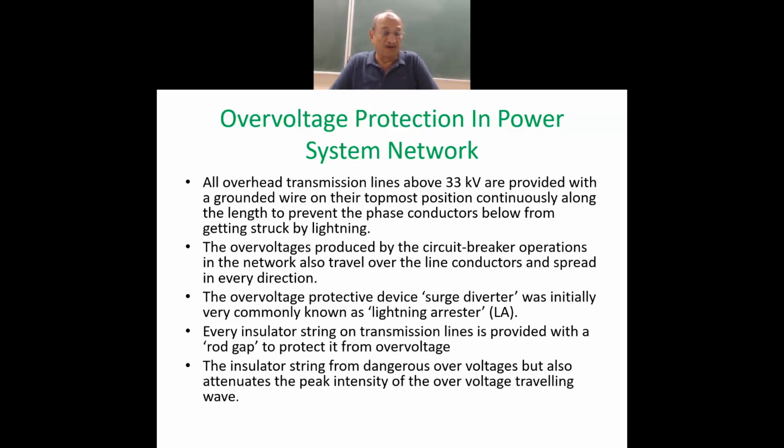We also learned in detail in the last lecture how the lightning arrestors or surge diverters function. They let the peak of the overvoltage be grounded, and let pass only what is left in the direction the traveling wave is traveling. The voltage across the lightning arrestor is able to propagate further, and it is cut by the peak value.